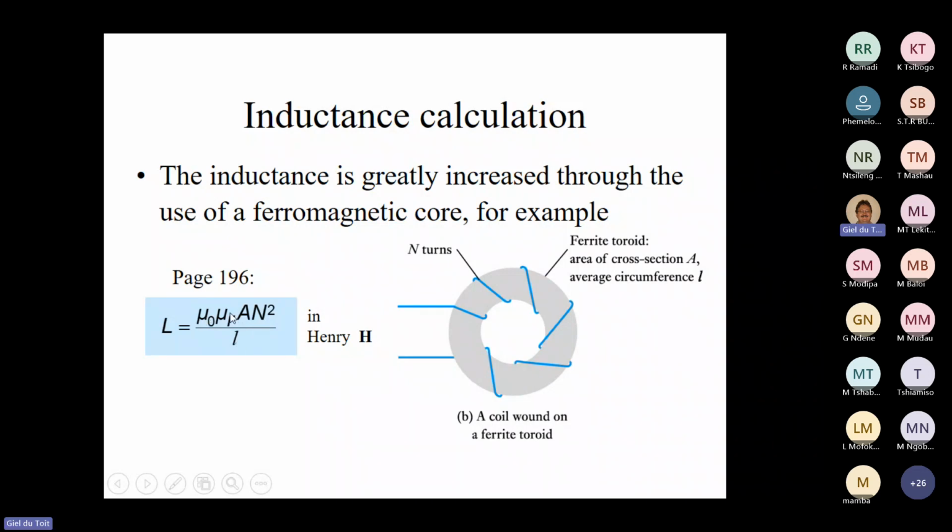All right, so mu r is the relative permeability, and if I slide a core in, like a rod, a pen or a pencil but made out of metal, I can slide it in and out of the coil. In that case, I can amplify the signal or the inductance. I can amplify it by times 10, times 100, times 10,000. It depends on my core. So this gives you a little bit of background about inductors.